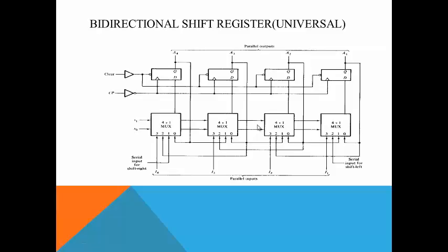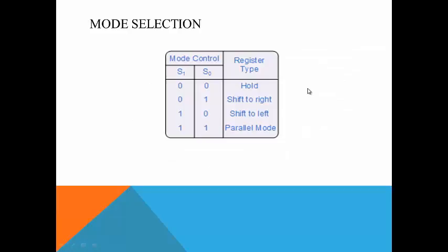Now, the bidirectional shift register can move in either direction, shift right or shift left, in parallel and in serial mode and so on. This is made possible using 4:1 muxes with control signals. So you will have mode operations depending on the select bits of your mux.